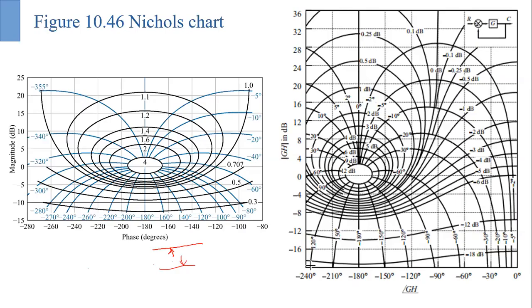That is why Nichols designed a special chart based on the M and N circles, where the magnitude is in dB. They have circles like this. These are your magnitude circles, and also the N phase. So, magnitude versus phase, he mapped those M and N circles and generated this chart, and this is known as the Nichols chart. A clearer version is shown here.